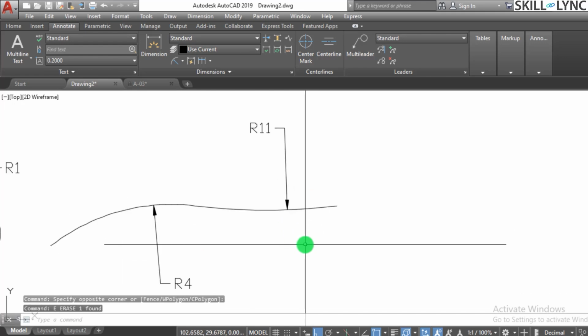Now, when to use a radius and when to use diameter depends upon whether you have a hole or a cut, a circle that you need to create inside a particular sketch or a model. For example, you want to create an opening or a well kind of thing. In that case, you provide diameter. But if there is a surface or a curve or an arc, like a fillet arc, it is always suggested to go with the radius.